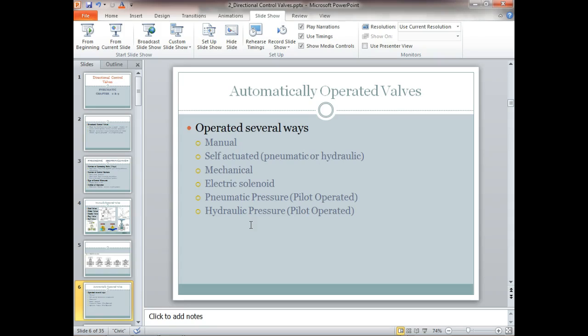It's basically got 4 bolts on each side that run the extension of the cylinder, and you loosen them up and break off the rod cap and the end cap, and you can pull the cylinder out and replace the whole thing. So the advantage of those, they would be more expensive, but they would be what? Repairable. These guys are less expensive, but they're unrepairable.